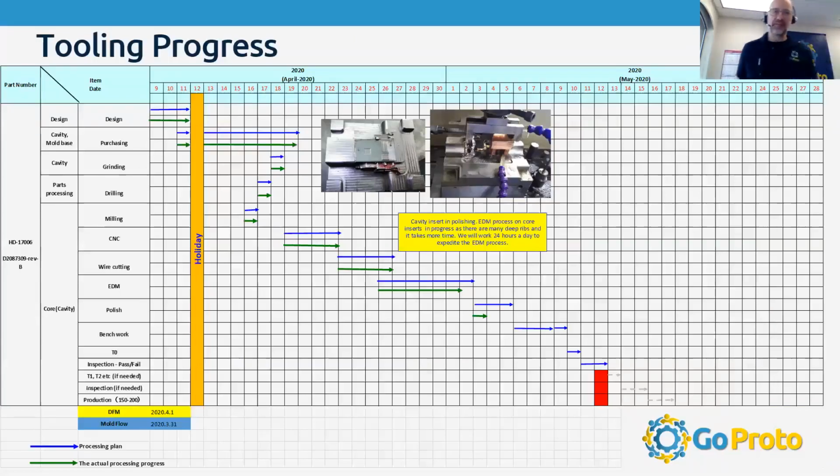Okay, and then up again comes the tooling progress report here, just to show that sometimes after T1, there are often, as I showed on that last inspection report, issues that come up, whether they're parts or dimensions or material, surface finish, something like that, that require a spin on the tool, a quick fix of it, and then a reshot of parts. Or sometimes at that point you get your first articles in and you realize, oh, I made a design error and I need to make some modifications, or I want to add a feature. Then we can go in and quickly get that tool modified and then go back through what's called T2 or second articles and repeat that cycle.